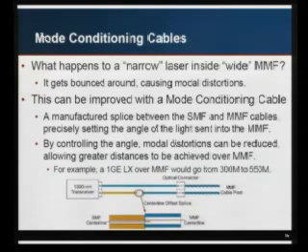All that is, is a manufactured fusion splice that sets the offset between the single mode and the multimode. So you want it to hit at a certain angle that minimizes all the multipath reflections inside the multimode, and lets you get longer distances.